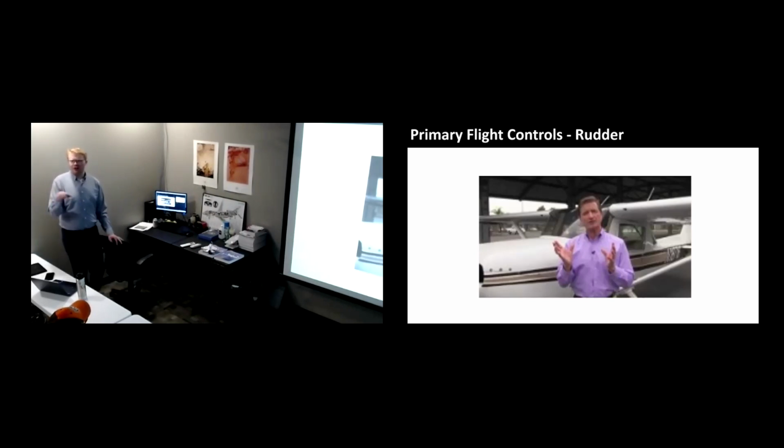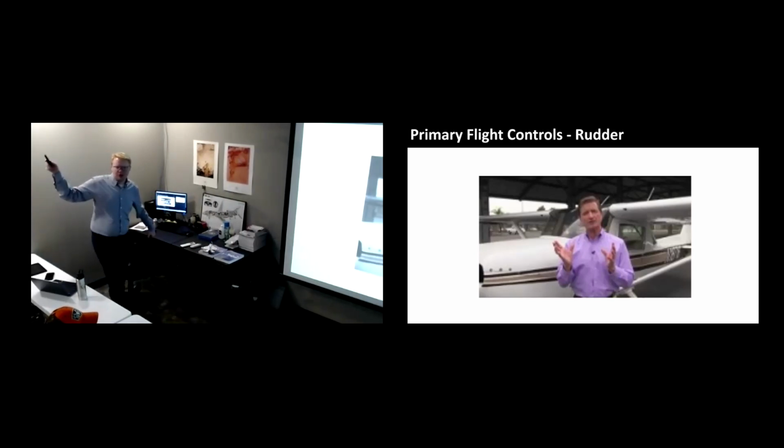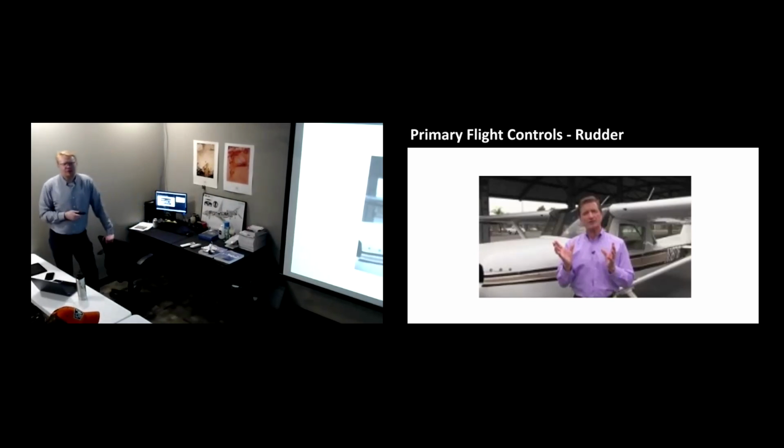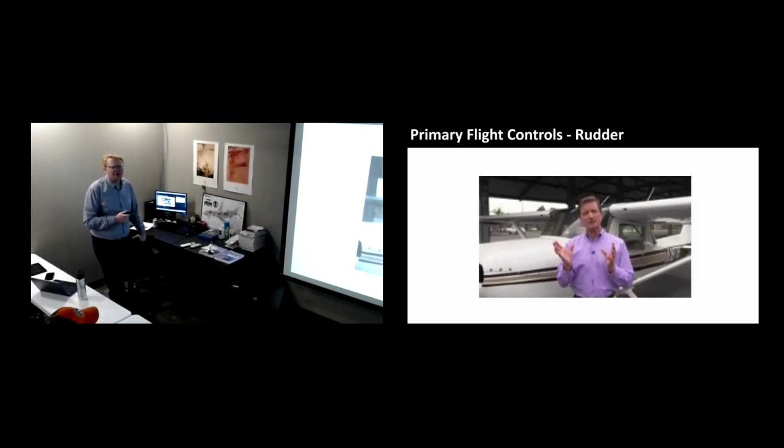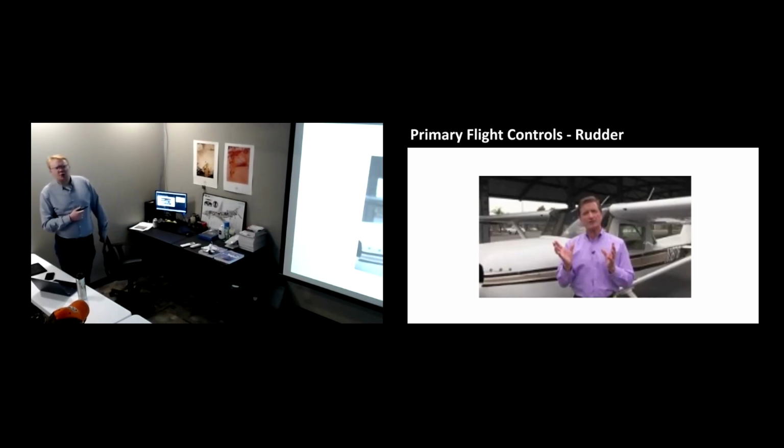Can you guys share your experiences on it? Anyone want to go first? Makes it a lot easier to make the left-hand or right-hand turn when you use the rudder. Yeah, it does, doesn't it? You give a little bit of rudder in either direction, and that plane just wants to turn by itself. Right. Have you noticed maybe a difference at high speed versus slow speeds? Probably high speeds, you're going to get a little reaction to it. Yeah, because of the velocity. Would you consciously notice that when you're at a slower speed, you'll need more rudder input to have the same aileron input?